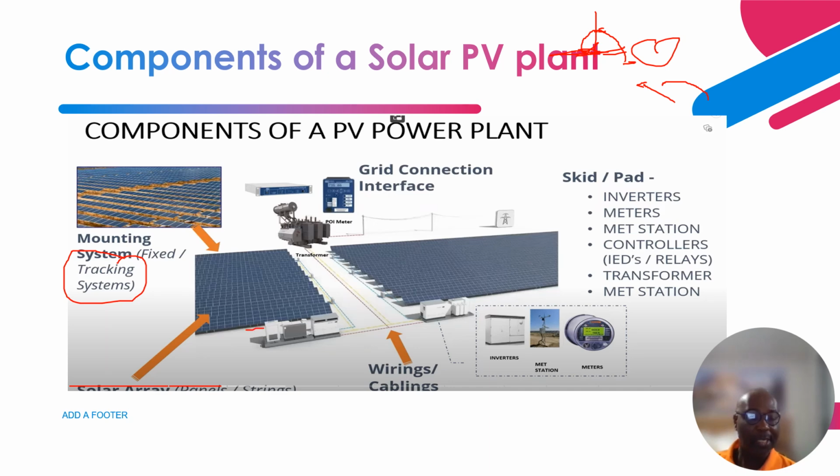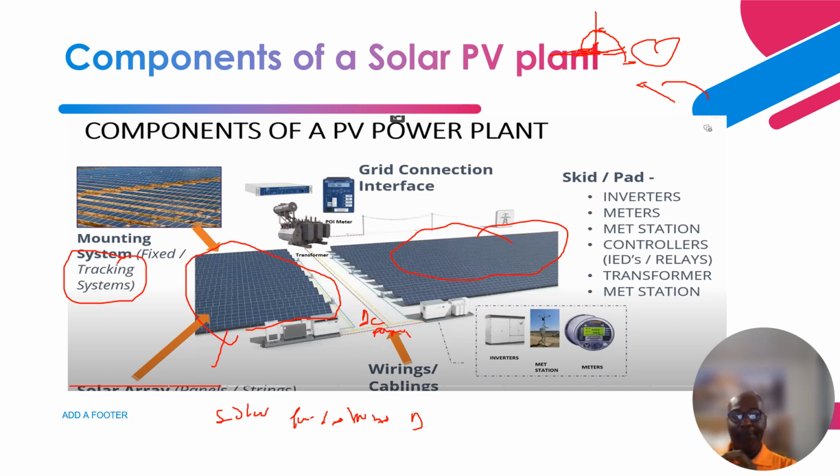So these are the solar panels, or modules, forming an array, and this is the equivalent of the array. You have DC power being generated, and the DC voltage created might be lower, so it goes through a step up, through a DC to DC converter that steps up the voltage to a higher DC voltage before it's fed to the inverter. So this is the inverter, and after that it goes through the step-up transformer.